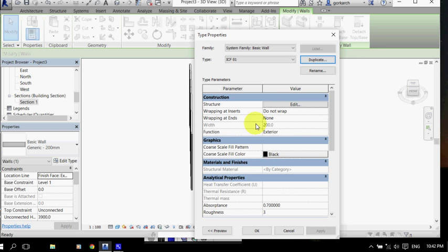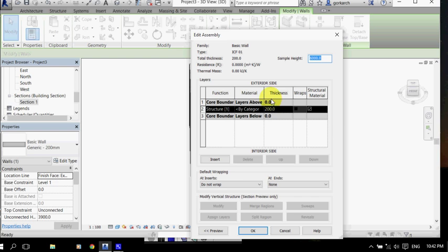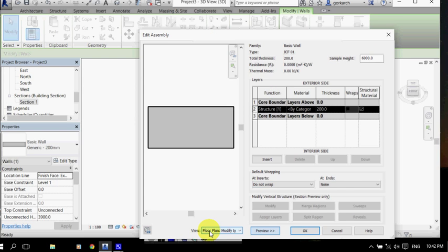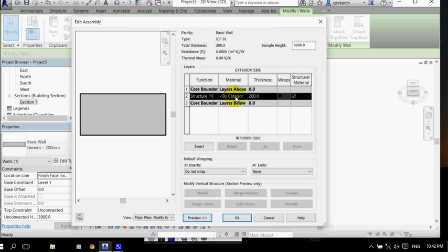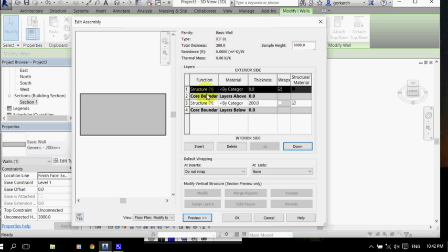And under that name, I'm going to edit structure. Here, I would probably open preview, so it shows me the layers that I'm creating. And I'll build some additional layers. So, insert layer. This layer I'd like to move up, and I'll switch it from structure to substrate, level of importance 2.